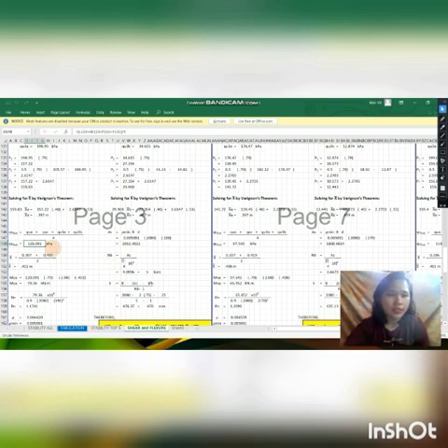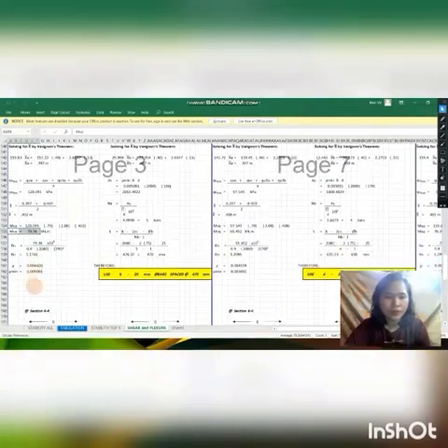So using this value for our QU average and the X bar, we will use these values in our MUy, which is QU average times the X times the B times the X bar. So we will arrive at the answer of 79.36 kilonewton meter as our moment.